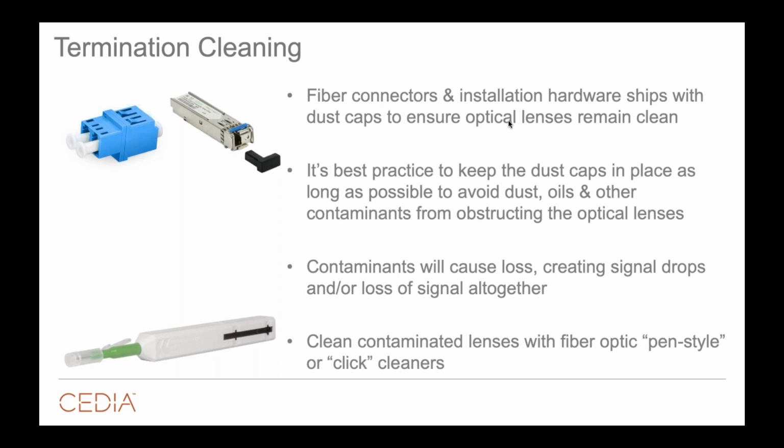If you are going into an installation where there's cable that's already been installed, pre-existing connectors, patch cords, network equipment, whatever it may be, it's a good idea to clean those before you use those, because all it takes is a little pollen in the air, some dust, oil from your fingers, leftover barbecue sauce from lunch, whatever it may be, that can get on those optical lenses and disrupt the performance.